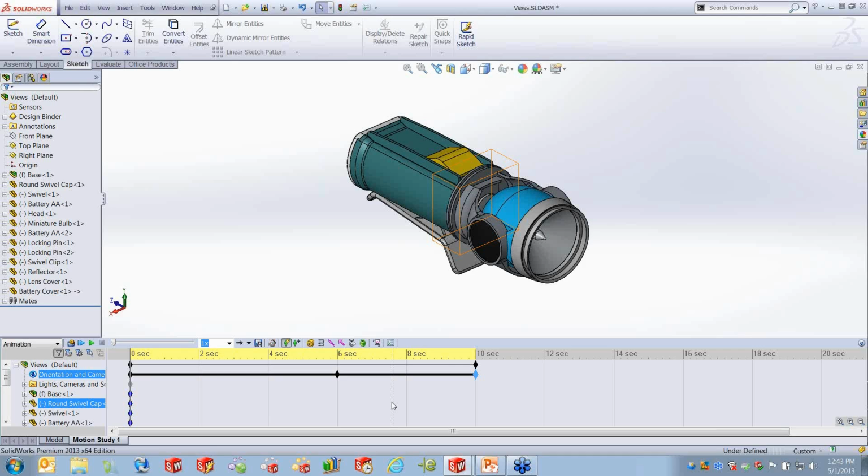You can use the isolate command. You can change the component display, hidden removed, hidden visible, or the appearances. When I talk appearances, I'm talking color, specularity, shininess, all those things that we deal with in appearances. The great thing is that's all done the same way as we've been talking about.